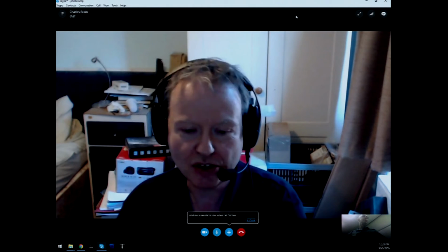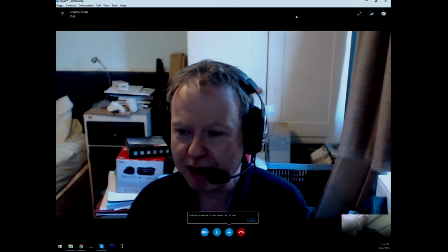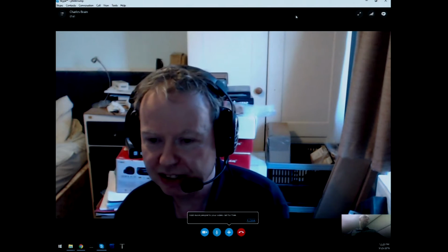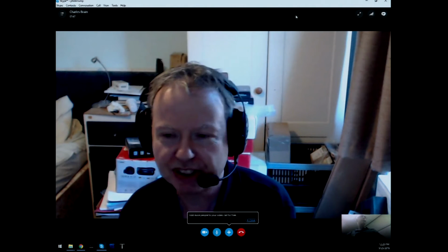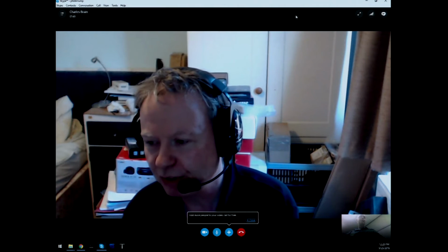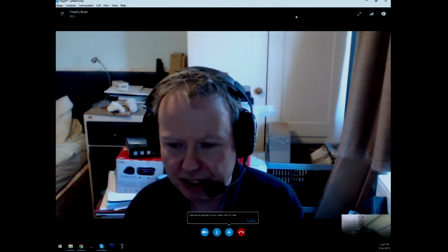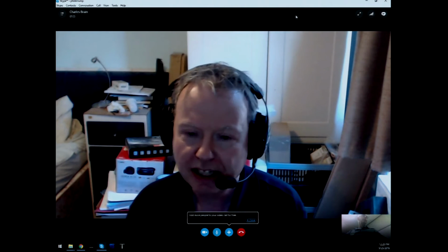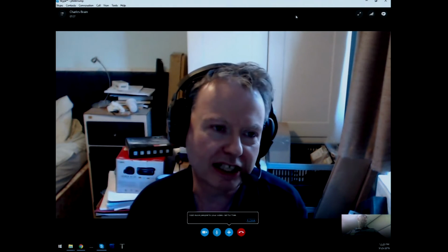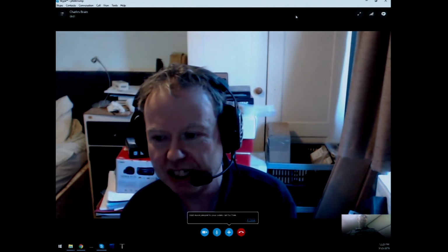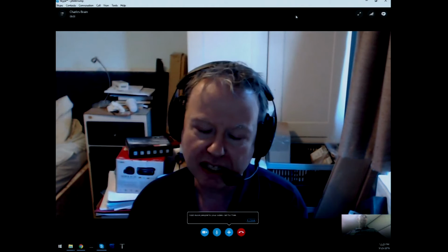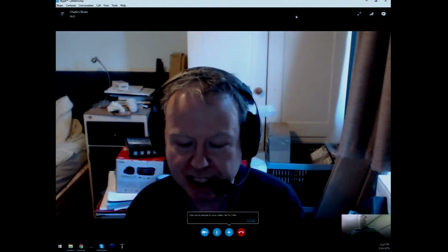The other advantage, of course, with the Lime is that the USB bandwidth is dramatically increased. I think USB 2 can support I can't remember how many gigabits per second, but it makes a phenomenal difference. And also, because the Lime's got two receiver channels in it, we'll be able to do stuff like digital pre-distortion of the waveform, because the DPD that I've implemented in Express has to be set up manually.